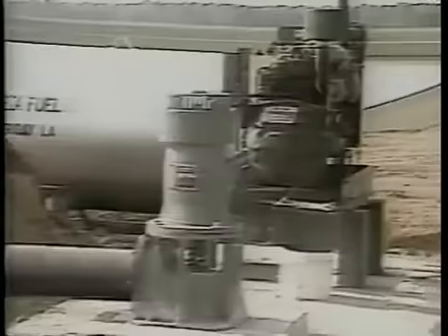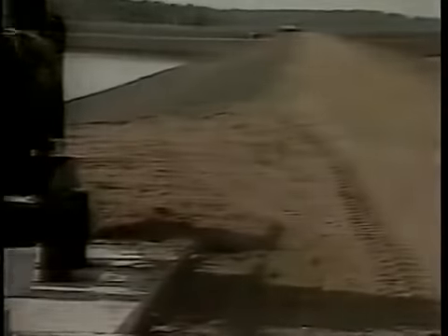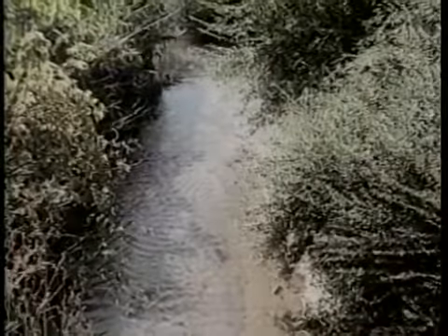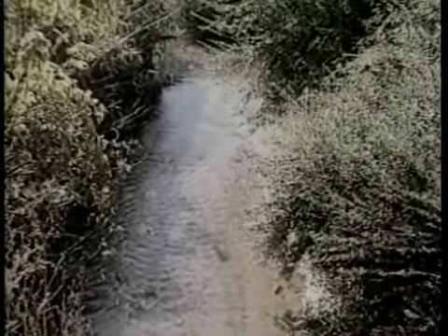The basic composition of compounds in water is determined by the location of its source. For example, well water obtains ions directly from mineral deposits of the aquifer in which it is located. Therefore, water from a limestone aquifer will contain large quantities of calcium and carbonate ions. Surface water will contain ions dissolved from the stream bed and from runoff over land into the stream. In many areas, various types of water may be obtained by drilling at different depths.